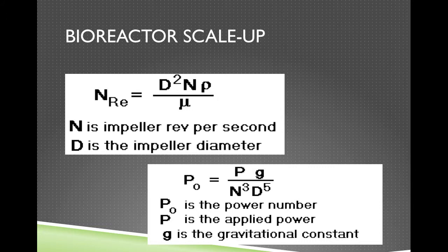First, the density and kinematic viscosity of the solution is inputted for the user. This data is selected from previous experiments and is required for the power equation. The module requires 3 inputs from the user. The first is the diameter of the mixing impeller. This is required in meters. The next is the speed of the impeller, which the user is allowed to leave as a variable number if they choose. The final input is the volume of the bioreactor, which is given in cubic meters, as this is a large-scale process. This input is also able to be modeled as variable.